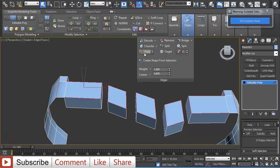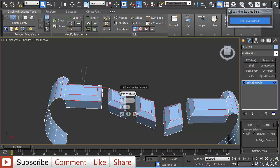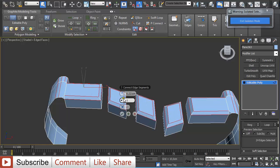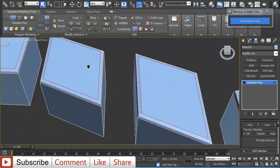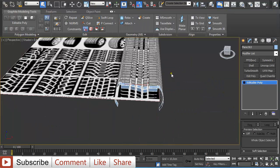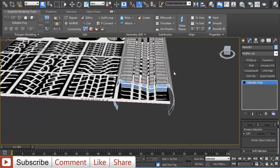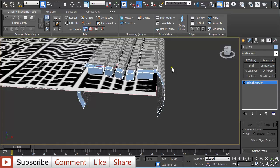And then going to chamfer, hold shift and make a small chamfer, and 0.1 centimeter will do. And this way we get a little bit less harsh edges.